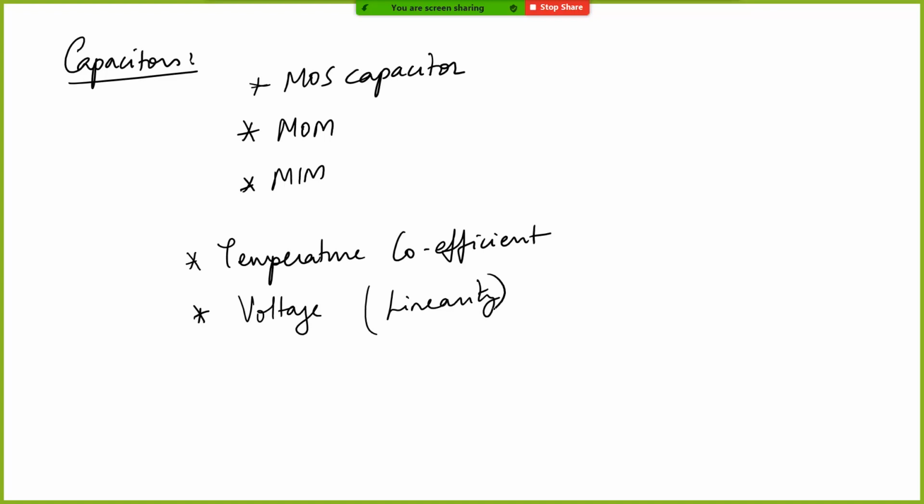When there is current flow in the chip, as the chip is functioning, as current flows, there will be Joule heating, right? Because the wires and everything will have a certain resistance. And so there will be I squared R loss happening in those metal lines, and also in your transistor, right? So this dissipates as heat. So typically what happens is there will be localized heating on the chip.